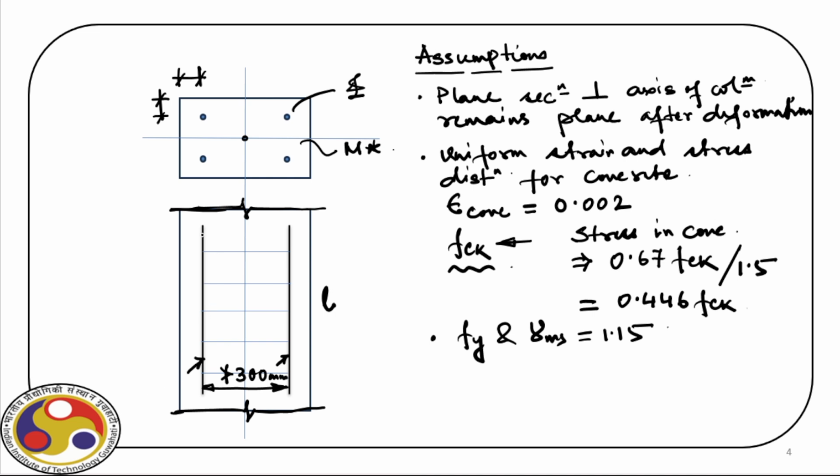If we have a distance more than 300, then we have to provide at least a minimum diameter bar here. So we have to redesign or readjust the amount of steel. We can find out this amount of steel from the design, then we select the bars. Remember, we have to select minimum 12 millimeter bars. And if we have by chance spacing more than 300, then we have to provide a minimum diameter bar in between.